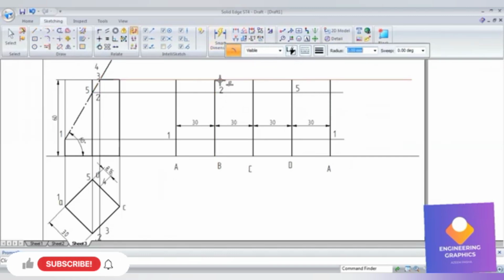Now using the arc by center method, we can cut the arc from vertical edge 2 to 3, that is 8.16. We can give the radius 8.16 and cut the arc. Okay, and the same length again from 5 to D. 5 to D is also the same length, so the radius is the same, 8.16, we have to give and cut the arc.